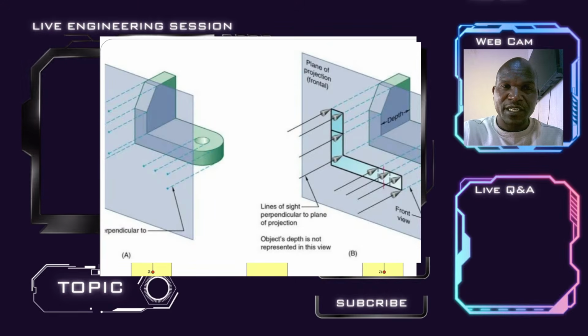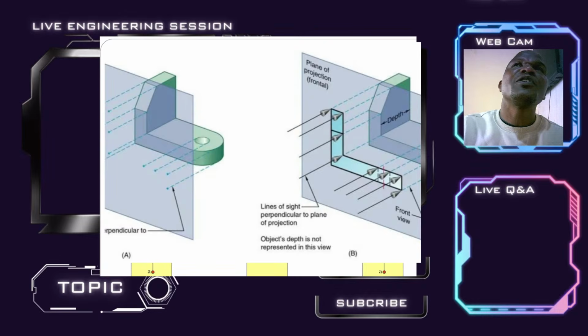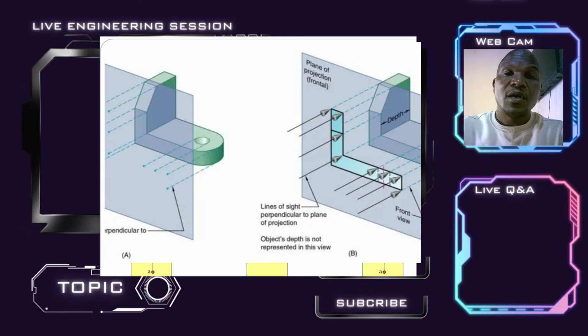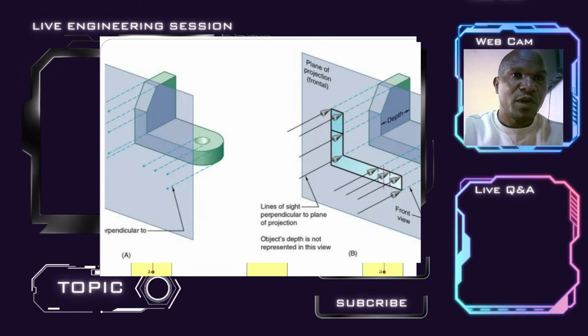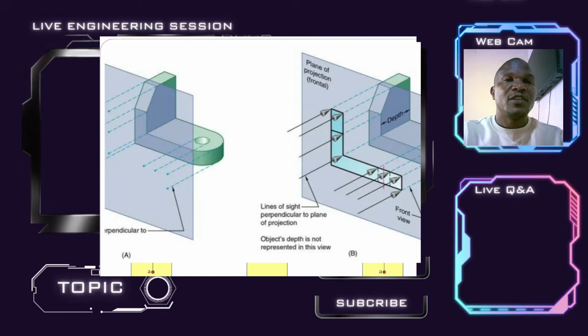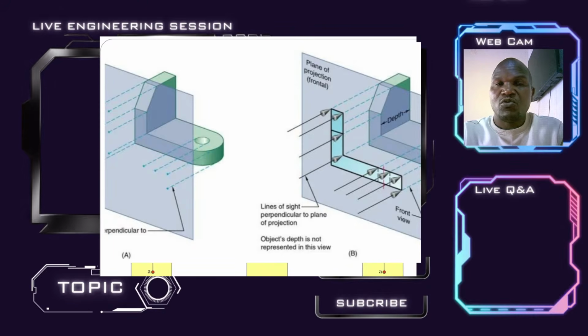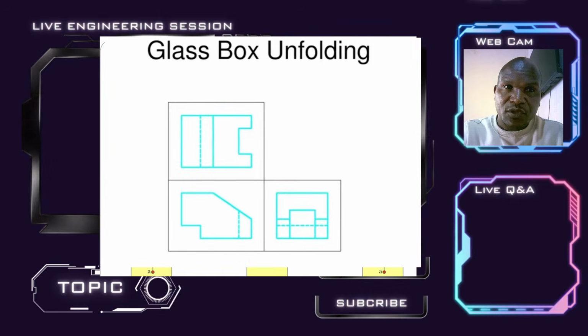Repeat again: in the front view, you can only communicate to whoever is going to design or manufacture it that there is a hidden feature here. In this case, it's a hole of maybe this length, because when you show dimensions, they communicate exactly that the depth of this hole is approximately, let me say, 10 millimeters deep, or it's through, or just to a given length.